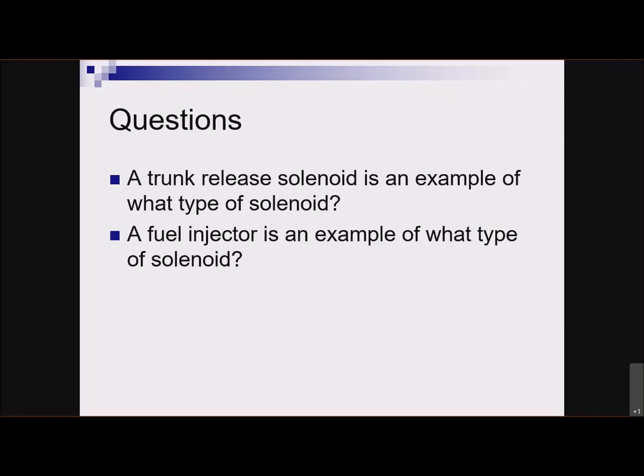What else would be liquid control? Things that control brake fluid, things that control transmission fluid. A more recent example, really common now, vehicles have variable valve timing. So there will be solenoids for the cam phasers controlling the flow of motor oil into a cam phaser, which can then advance the cam.